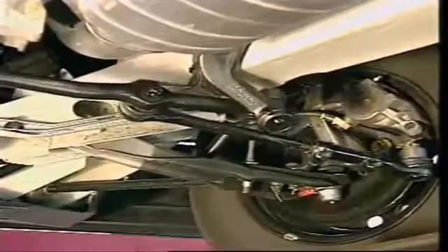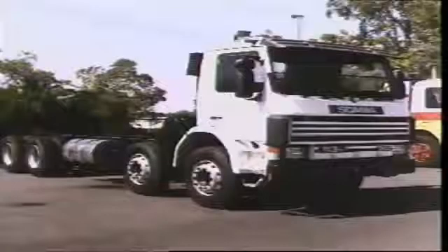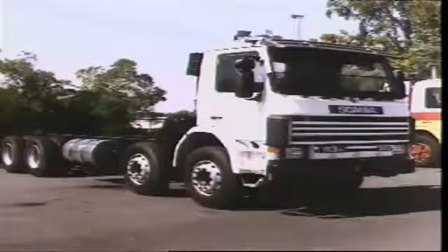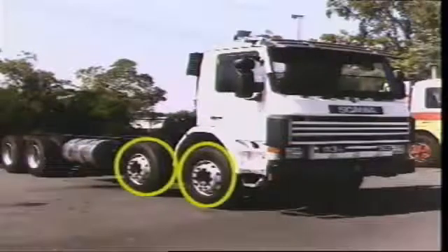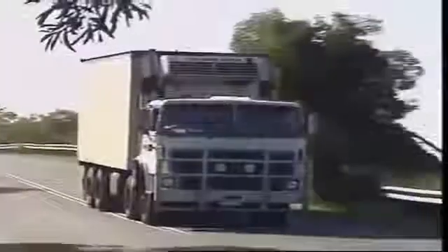This steering system has worm gearing. It provides a gear reduction and a 90-degree change in direction. It has more parts and joints than the rack type, but it is more robust and may be used on heavier vehicles. To allow heavy transport vehicles to carry extra weight, two steering axles may be used. They're connected by a link to a common steering box. These vehicles are called tandem or twin-steered vehicles.